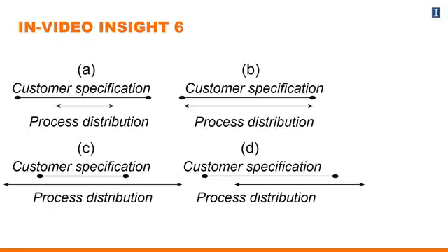So what you can actually infer from C is that if you have a CP value, a process capability ratio, that is less than 1, there's no point of even calculating the index, the CPK, because then the CPK is also going to be less than 1.